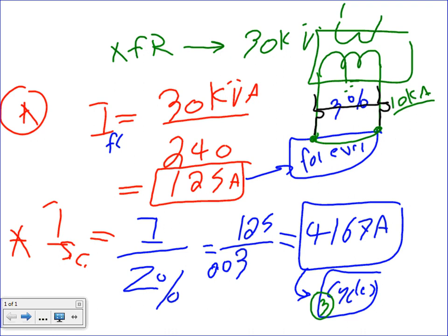Without getting too much into that one, guys, we will be using a short circuit calculation. There are 2 things that you need to know about. Number 1 is the equipment rating. This equipment is rated for 10K. It can handle 10K. They rate them. And the second thing is the available short circuit. The available short circuit, we calculated it. Here's exactly what we calculated, guys.